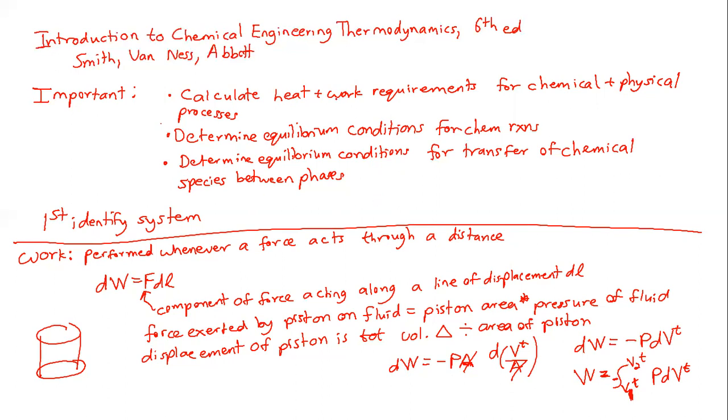In process design, we're primarily concerned with steady state operation. And so these types of constant properties are very important. The reason that I bring up this one about the work is because it is helpful for better understanding why you have higher costs for compression of a gas than if you're pumping a liquid.